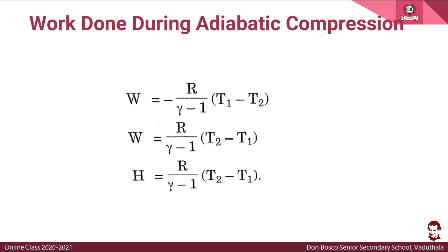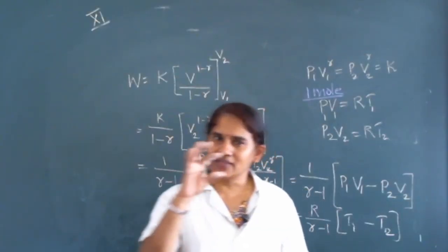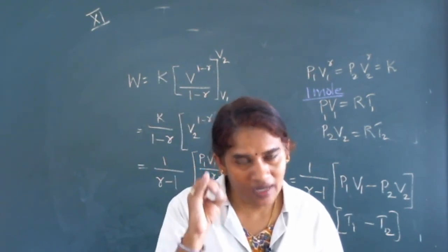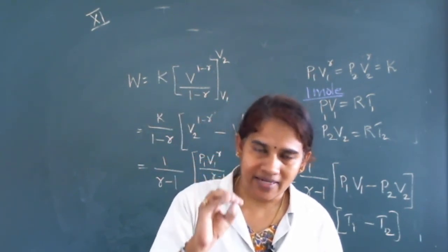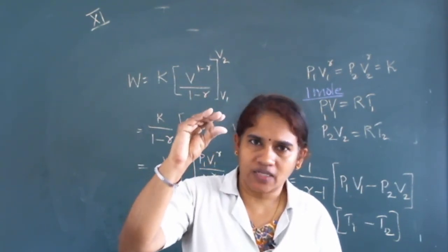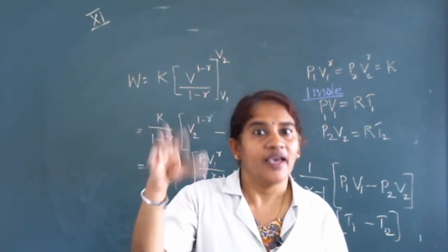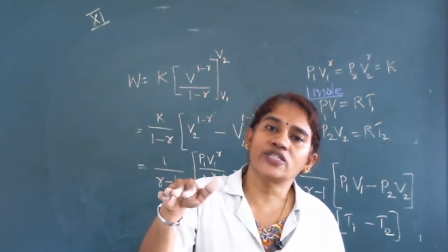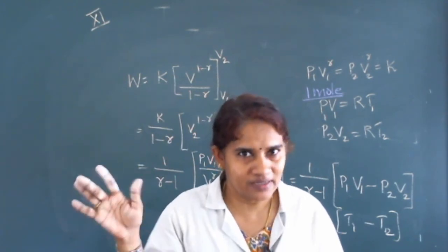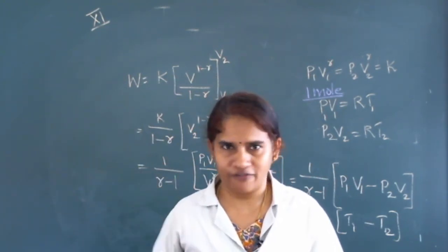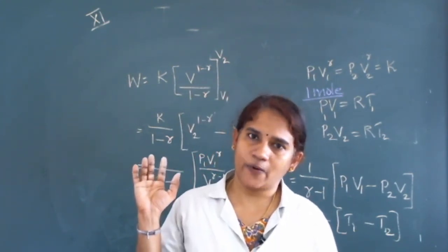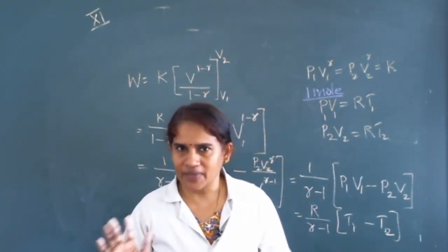Okay, that's all for today. It's derivation, right? So we have seen what is isothermal, its derivation, and adiabatic's derivation. The steps are the same. First, the respective equation, work done is equal to PdV. Integrate, apply the equation of the isothermal case for isothermal and the adiabatic equation for the adiabatic case, and we modified the result. For compression, we had given a negative sign. Okay, with that everything is completed.